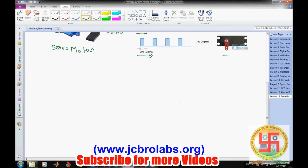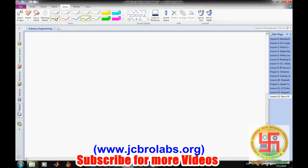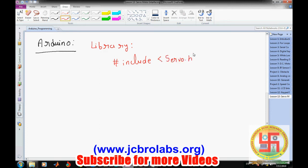Okay, now comes the interfacing part with this Arduino. Arduino provides a library for interfacing this servo motor. We have a library which is #include, and this library has to be included: servo.h. Now within this library, the first step is we have to create a servo motor object. We have to create it, only then we can access all other properties of this one.